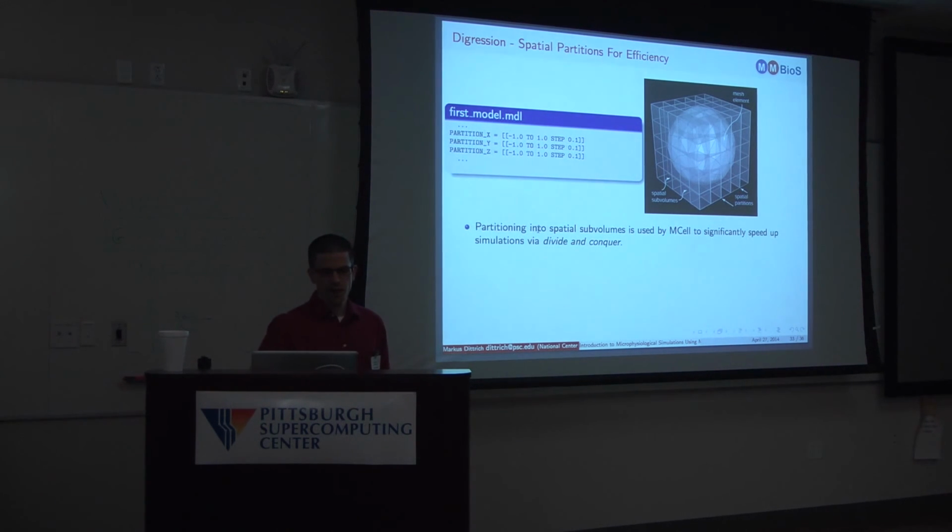Faster simulation. Once you start setting up a real production simulation, you should spend some time with this partitioning. The way to do that is to start off with some partitioning scheme. You could have maybe a 50 nanometer partition size or something like that. Then you run the simulation, you write down how long it takes. You decrease the size of the partitions, and if it runs faster, you keep going until at some point you notice it's actually not running faster anymore. There's a sweet spot that you can find fairly quickly after running maybe 10 simulations. That is the ideal partitioning for your system.